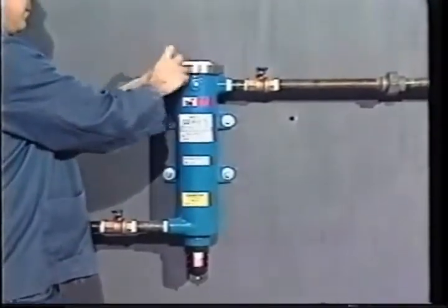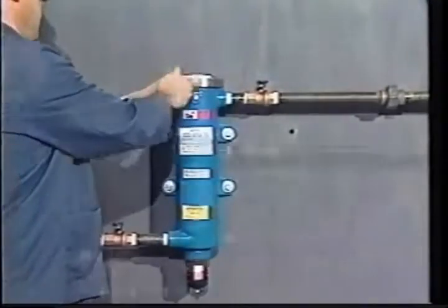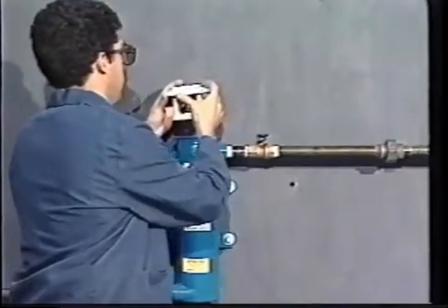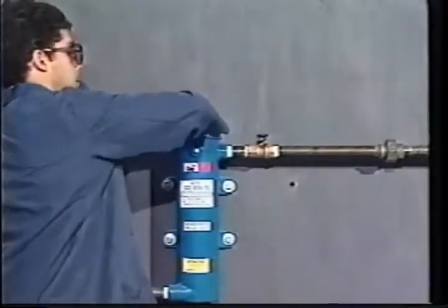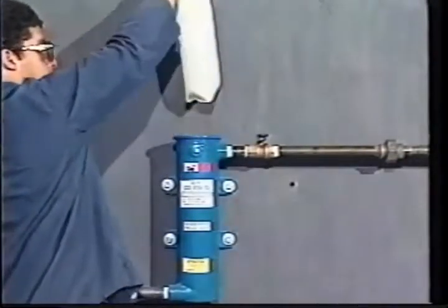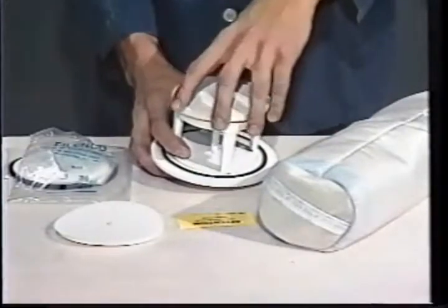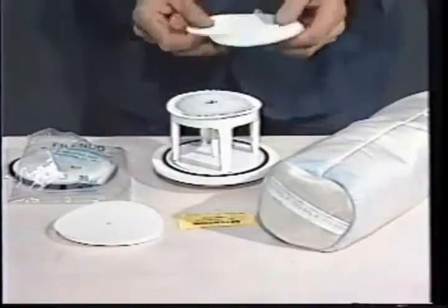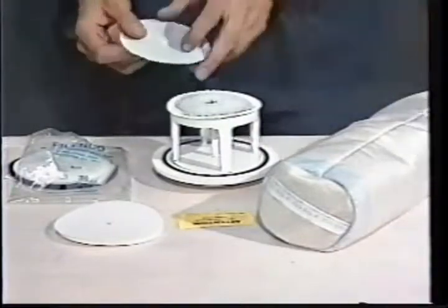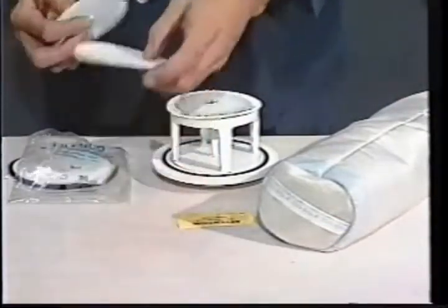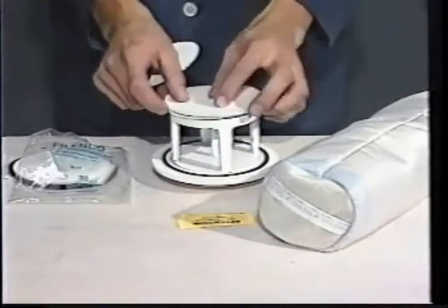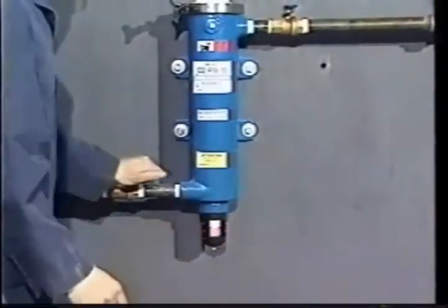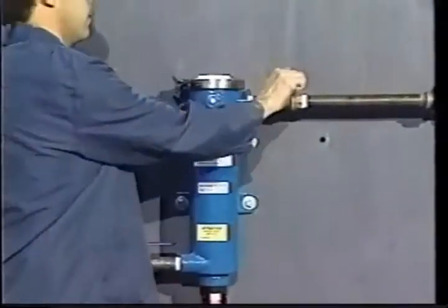Once pressure has been relieved, the knob securing the V-clamp is unscrewed, the clamp and cover removed, and the desiccant bag pulled out by the convenient strap. The lower stainless steel screen is unscrewed so that the old disc set can be removed and a new one installed. The change is completed by snugly reinstalling the lower screen and bag. Then the cover is reinserted and the V-clamp secured. Pressure is restored, first opening the upstream valve and then slowly opening the downstream valve.